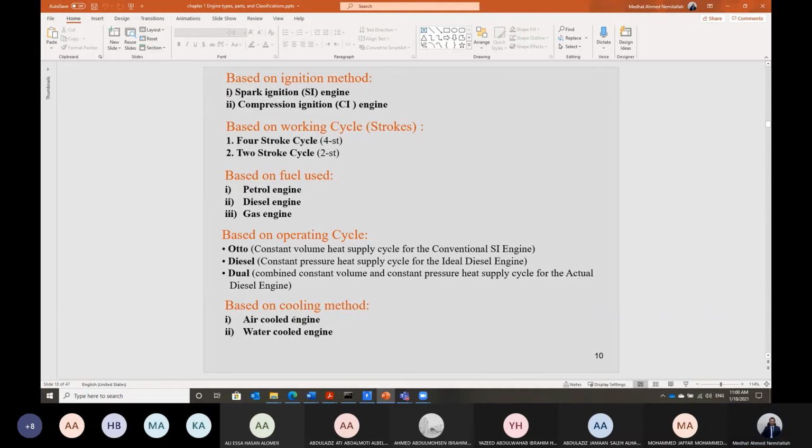In the case of a small engine, like a motorcycle engine, usually the motorcycle engine is air-cooled and is a single cylinder engine. So the engine power is low and the heat generated is not that much. In this case, the engine can be air-cooled. Usually they fix multiple fins around the engine to increase the surface area exposed to the air. Then the engine can be cooled by the air.